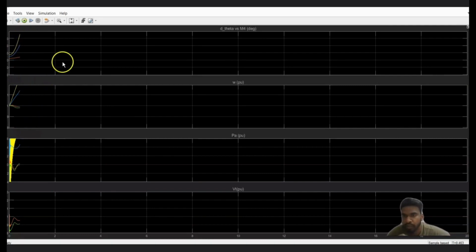Just now we saw it show a full stable system, reaching stability at 14 seconds, but now it trips out. It never shows any graph, and it becomes unstable at nearly 0.5 seconds. It took just 0.5 seconds to trip out, because the generator is able to produce 1767, but we are putting it over trouble, where we increase 100%, nearly 3000, so it couldn't reach stability.